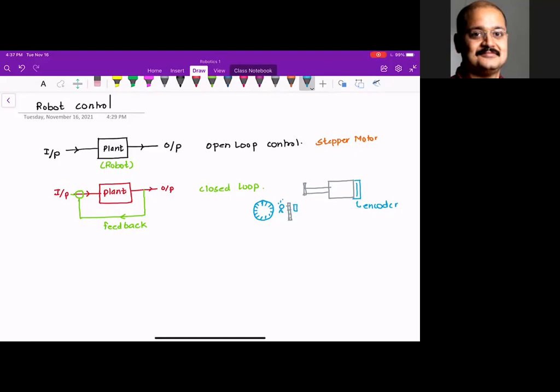So as this disk rotates, you are going to get some sort of an input or pulse width. So you know exactly how far that wheel has rotated. So you have some sort of a feedback. You have this encoder and you have this motor that is connected to a controller. This assembly is called a servo.